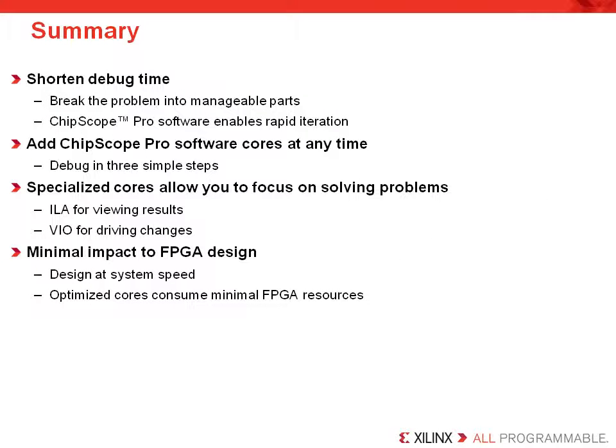In summary, the ChipScope software enables you to shorten your debugging time by 50% and enables rapid debugging iterations. It also allows you to test your design component by component. ChipScope also enables you to test any node in your design and to test many nodes at once. You can add ChipScope cores at any time, either during design construction or after your design has been made.